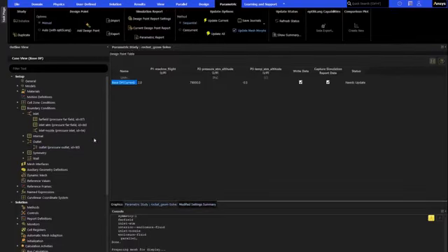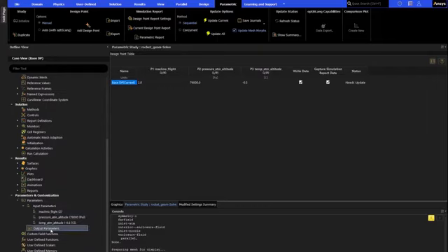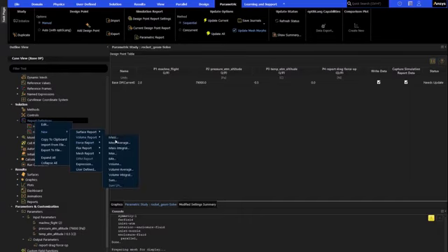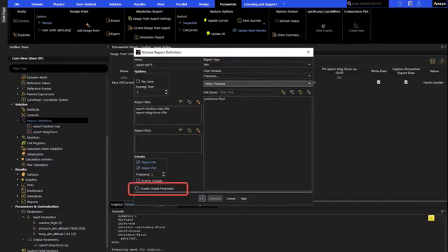In this case, we'll make sure our input expressions are set for the far-field inlet and outlet boundary conditions. To set the output parameters, we can select existing reports, such as the already defined drag force on the rocket, or create a new monitor report, selecting the option to set as an output parameter in the report definition pane.